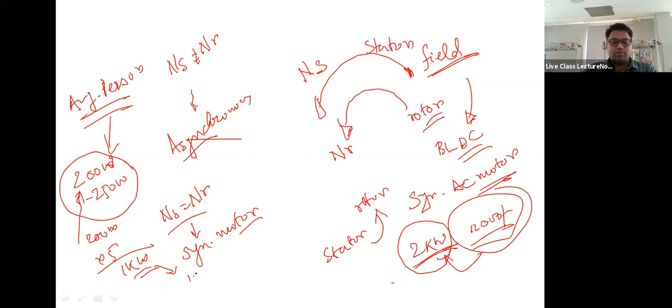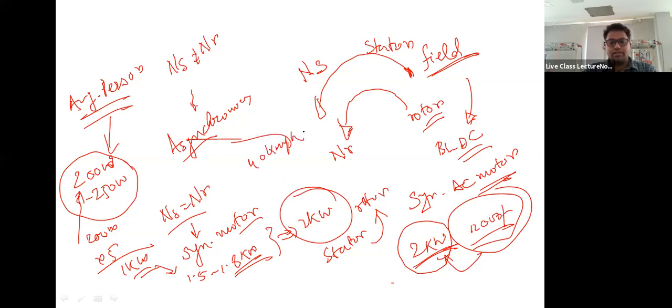So approximately 1.5 to 1.8 kilowatt of motor power is needed. So they give 2 kilowatt so that you can have some speed also. That electric auto runs at around 40 kilometers per hour. So that is the average requirement for a person to be pulled by an electric motor. Isn't it interesting?